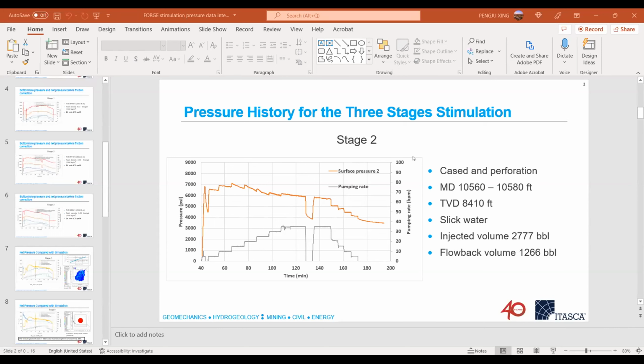Peter Lee, question? You want to come off mute? Actually, based on my experience on the oil and gas frac, because these stage 2 and 3, it's a cementing casing. Stage 1 is open hole. So you will see this different. With the cementing casing, even with the perforation, you have some extra friction there.